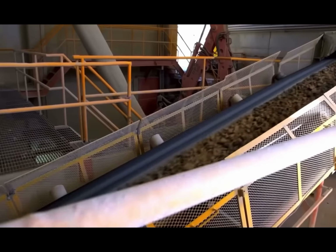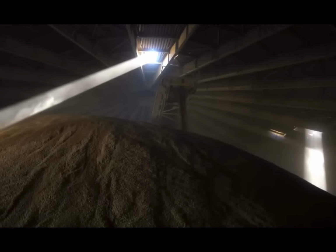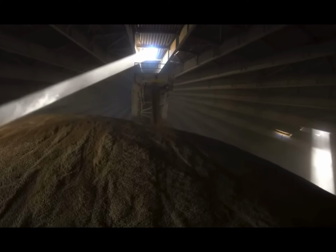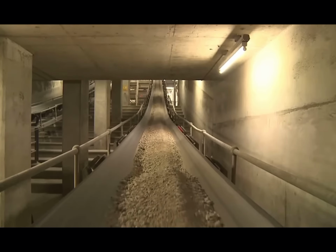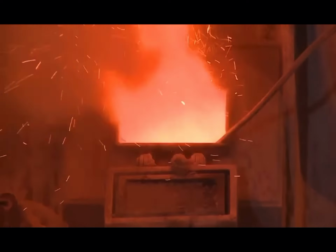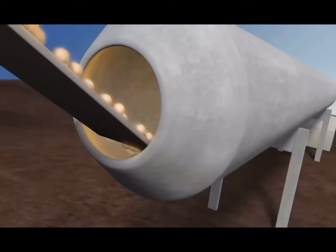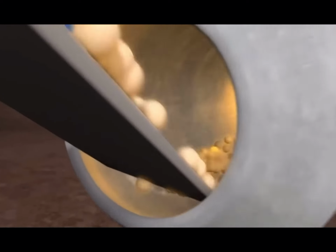The raw meal is transferred to a mill, which consists of a large rotating cylinder. Inside the mill, the raw materials are ground into a fine powder. This grinding process enhances the efficacy of the subsequent chemical reactions and ensures the uniformity of the raw meal composition. The powdered raw meal is then heated in a preheated tower, where hot gases from the kiln are used to raise the temperature. As the raw meal moves through the preheater, it undergoes partial calcination, which means that some of the carbonates in the limestone decompose to form calcium oxide, lime.